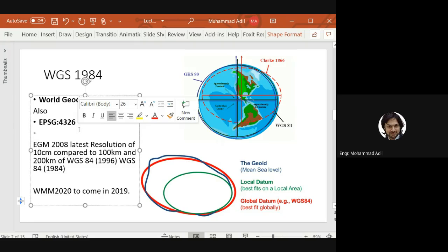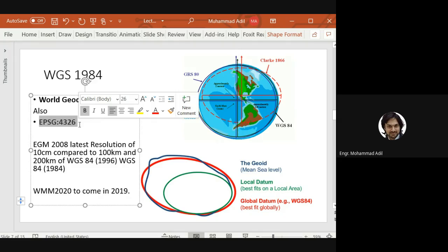and then you want to locate that on a Google map, which is actually based on EPSG 3857. So you need to convert 4326 into 3857, and software like QGIS or Quantum GIS and ArcGIS have the capability to do that. They have the formulas known. You can go online and look at these formulas as well, but you don't need to go into that detail because the software uses those formulas to do these conversions for you automatically.